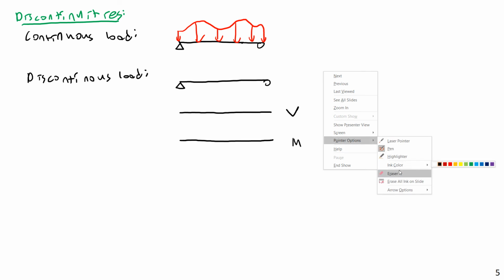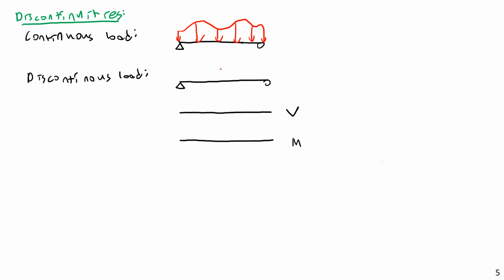Imagine you have a single point load, P, in the middle here, and if this is symmetric, this would be P over 2 here, and P over 2. What your V diagram ends up looking like is something like this. The P over 2 causes it to immediately jump up on the left-hand side to P over 2. Then it remains constant over to the middle load. Then it drops down by P to negative P over 2. And then it remains constant until you get to the right-hand side, where you jump back up to 0.